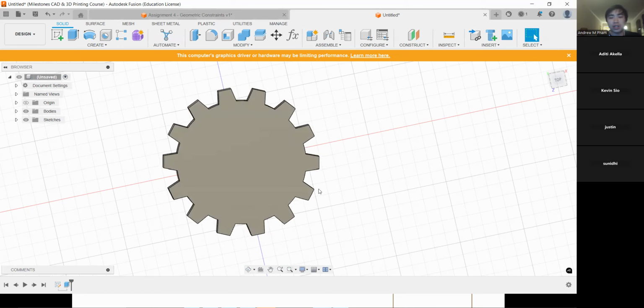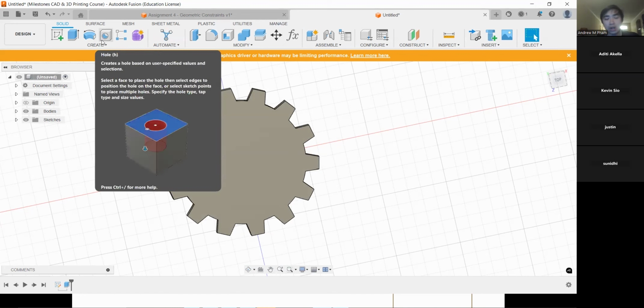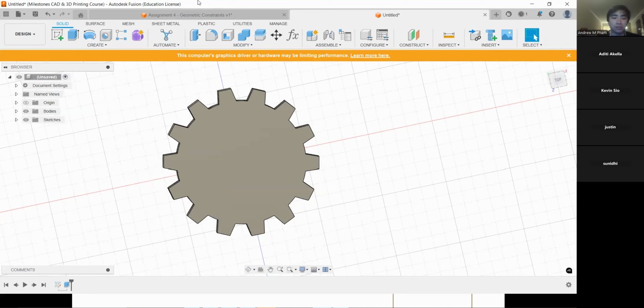And in our case, we want a hole in the center. So we could just make a sketch, draw a circle, and then extruded cut it away. But you do lose data, right? So what I mean by that is in the hole wizard, you'll see in a moment, there's a bunch of different options like hole diameter and drill bit taper angle, which is not really important for this scenario. But Fusion will treat a hole made from a hole tool and a hole made from a sketch and extruded cut differently when programming it in CAM.